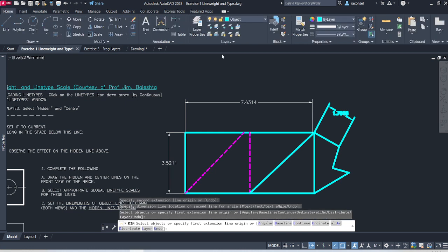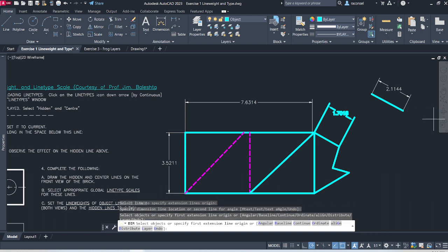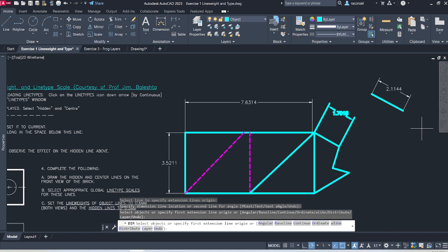Even if I'm drawing in a different layer. So I can go, hey, let's draw a line. Oops, escape line. I draw a line, and I slap down a dimension on that line. It did not change my layers. It's on the dimensions layer.